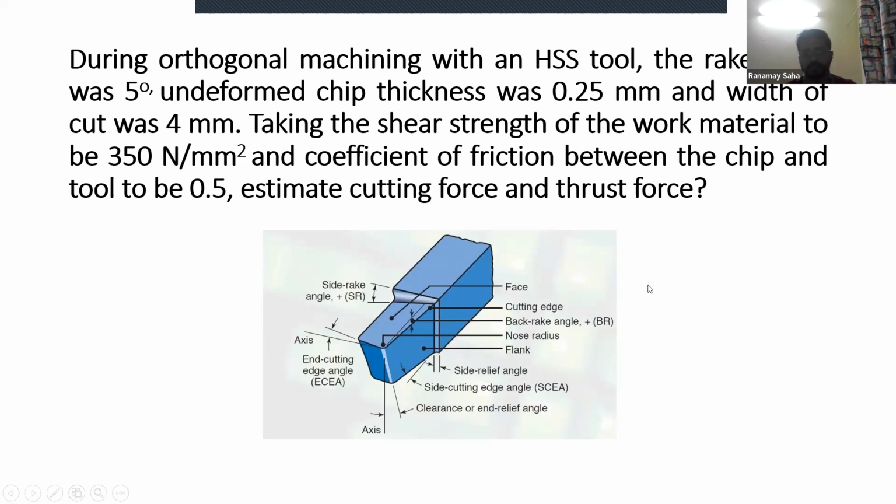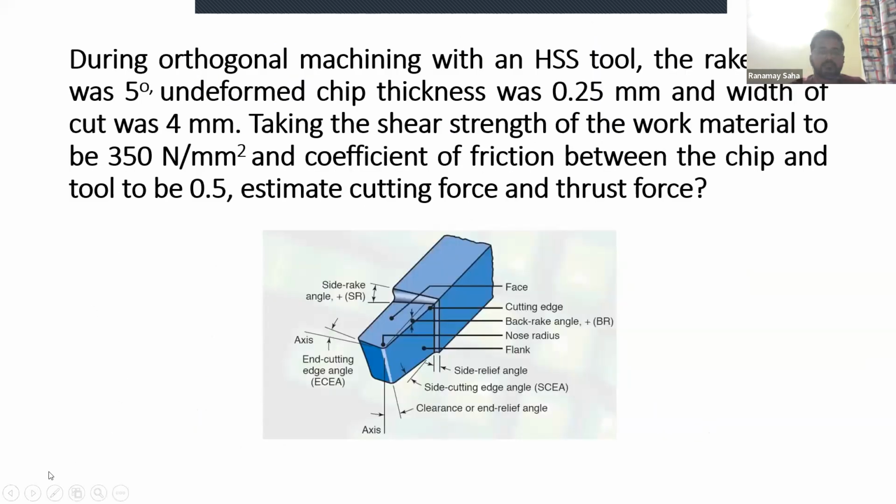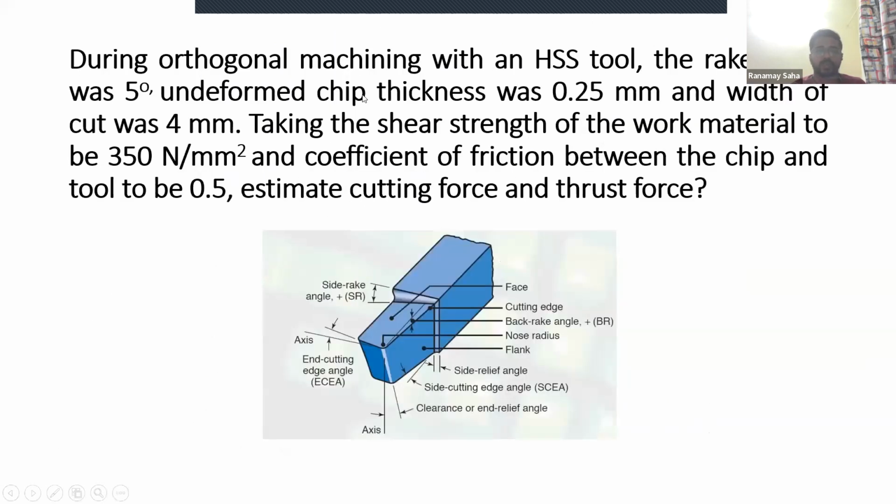So you'll be using the Merchant circle analysis in order to estimate the forces. In the process of determining such forces, you of course will need an angle called the shear angle phi, right? But the shear angle is not provided here.